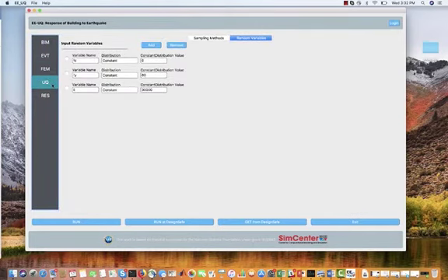Now when we come to the UQ, you see that we now have a number of variables set. When we loaded those OpenSees files, we parsed that file, and any variable that was set with the pset command is now automatically brought in here, and it's given a constant distribution. We need to change that constant distribution to something else. So we're going to give them all normal distributions. Let's say it's 10% standard deviation.